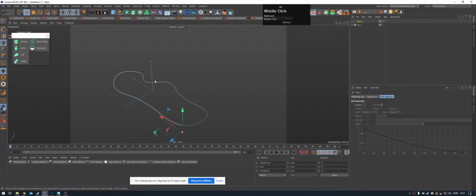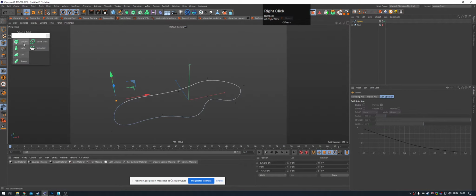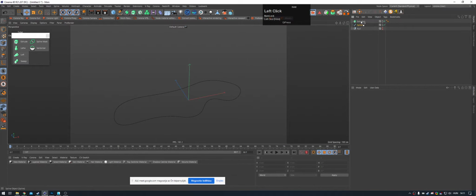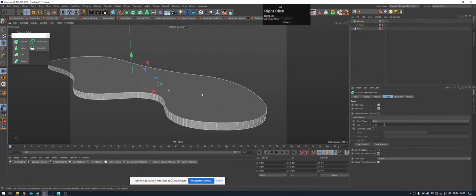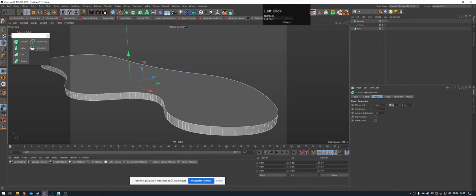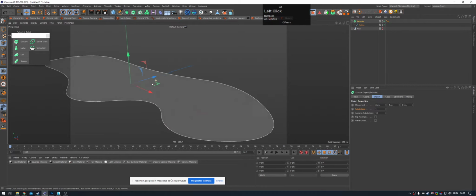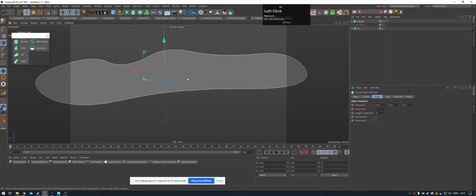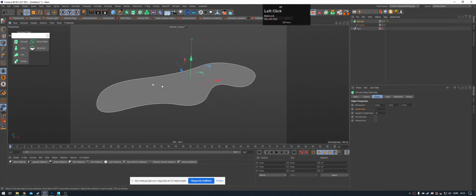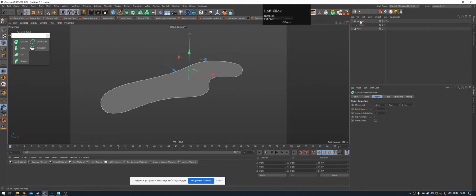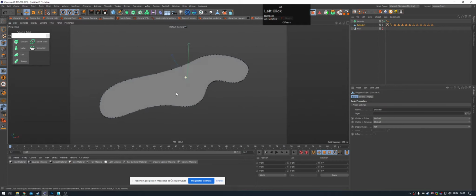It's easy, because you just have to drop it into an extrude surface with 0, 0, 0 movement. After this, you only have to press C and you get an N-gon.